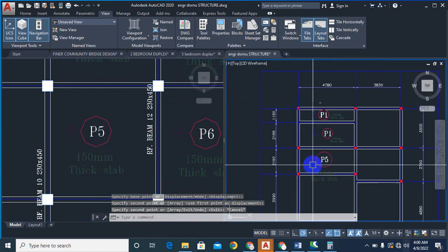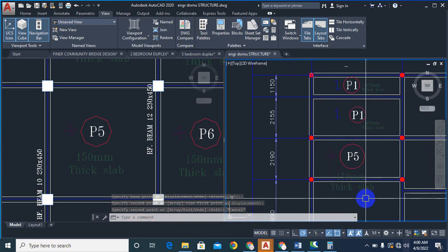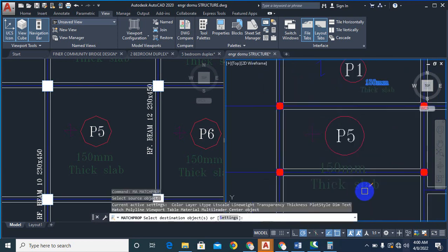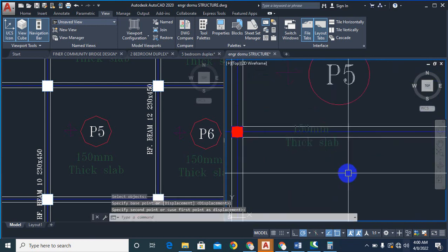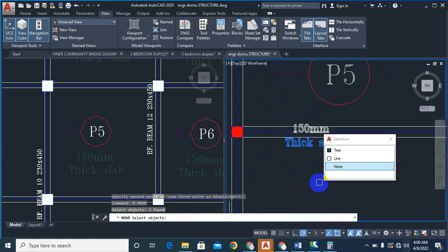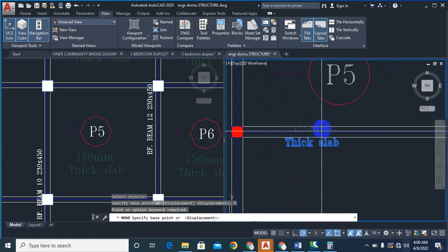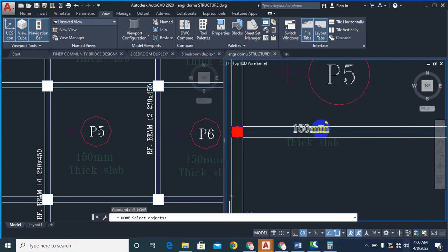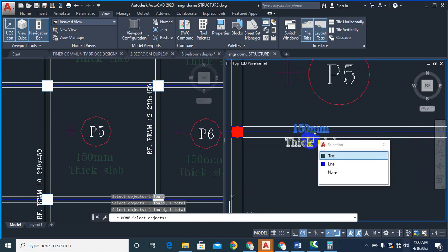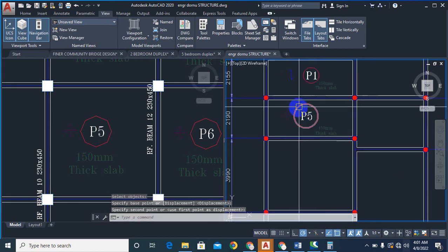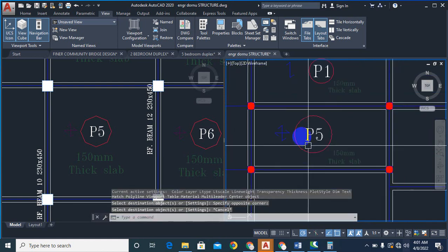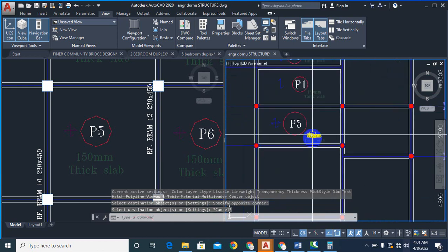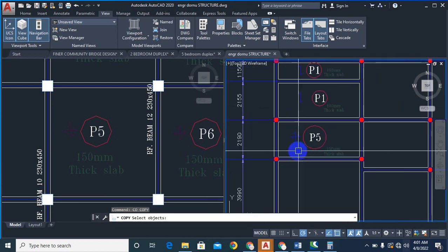I think this is also going to be a one-way slab. This is 2190, so it's also going to be one way. Please, I hope you know how to come about your one way, your two way. Okay, it is ly over lx. Ly means the longest span divided by the shortest span. So please make sure you do that.